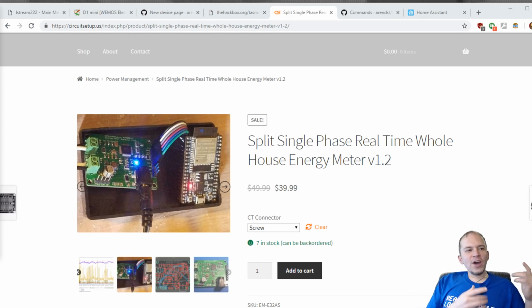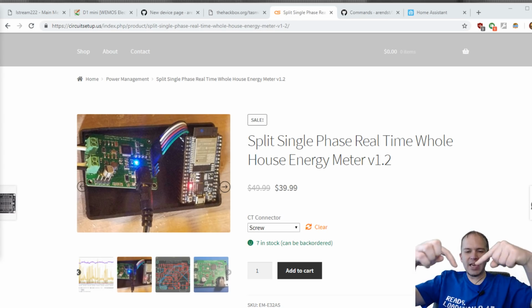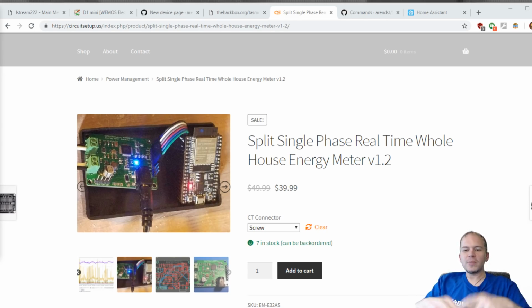I have one in my house where the 2 3-ways meet and come back out, they're on two separate circuits. So you'll cut the circuit off and turn off that fan in that room, but half of the other box is still alive from another circuit. So don't trust anything. One of those non-contact things are great.